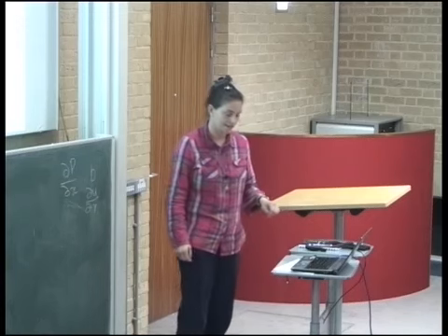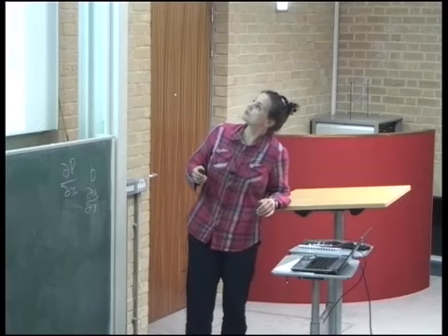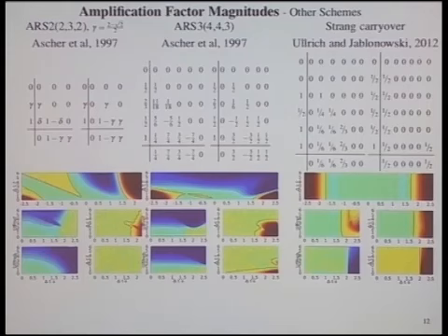Can you put it back up, sorry? Yeah, but you use about how many stages? I thought there were like 4 stages or more. Well, they do one explicit. Oh, yeah. One explicit stage. There's a lot of zeros in here which don't need to be calculated. Sure. So one explicit stage for the fast terms, and then you've got a third order explicit Runge-Kutta scheme, and then a final implicit solve.